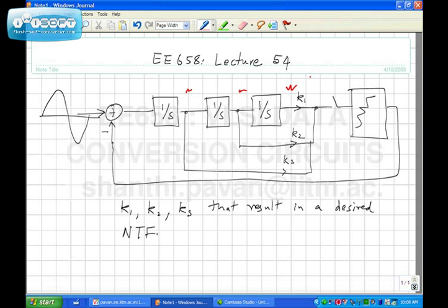One solution is to beat your head and figure out what happens when the integrators saturate. The engineering way of doing it is to make sure that the integrators don't saturate in the first place, so that this model is valid for all inputs within the maximum stable amplitude.